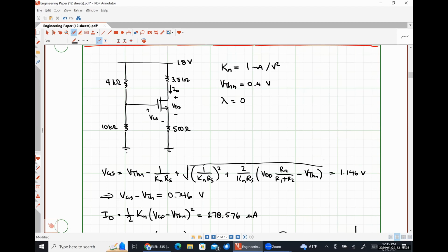I'm just trying to think if I've seen that particular configuration actually used, and usually the answer is no. Without this particular resistor right here, so with this as an open circuit, this configuration is what's very commonly used to bias what are called source follower amplifiers, which is effectively the MOSFET version of a unity gain buffer, or as close as you can get to it.